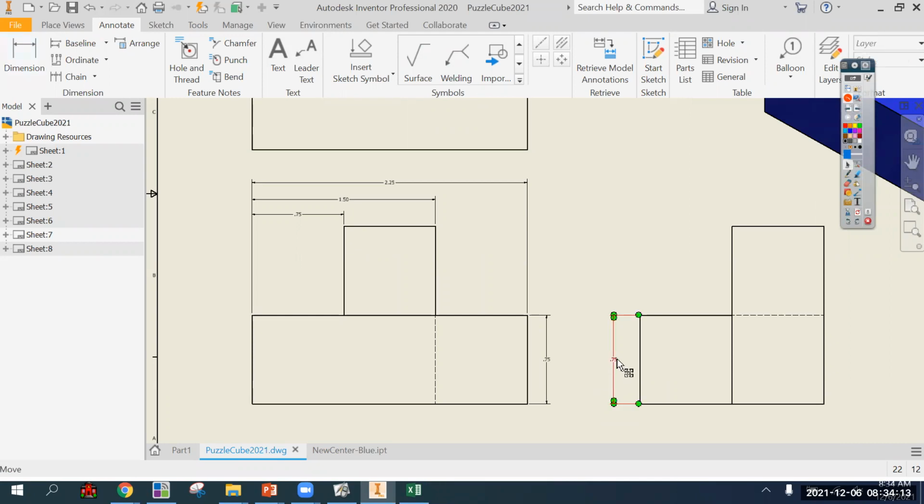Both places would be over dimensioning, but they both fit all the requirements. They both go to a contour. Neither of them crosses over a line or crosses over the view. If you only have one, it's not over dimensioning. So either one is fine. I tend to default to the front view just because, but it really doesn't matter in this case.